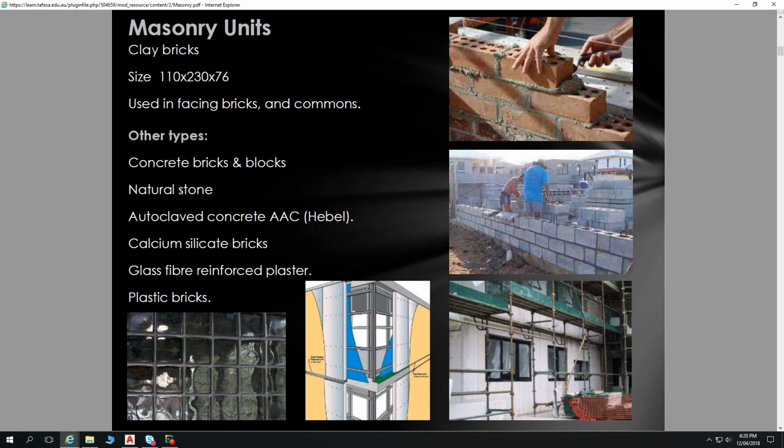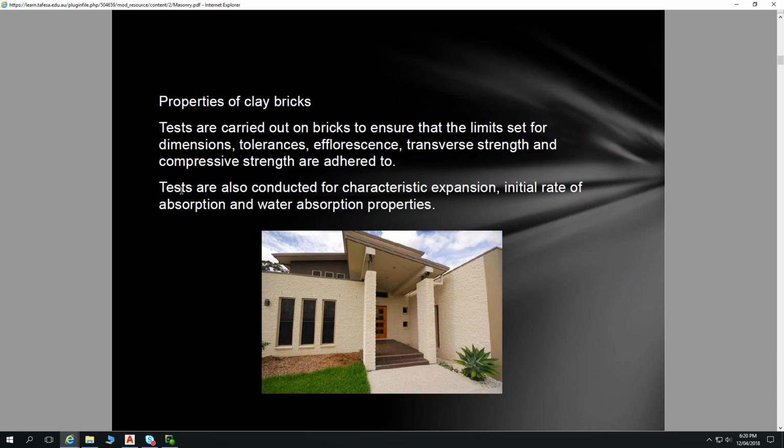But because we have to include insulation within our walls, it gets harder and harder to incorporate the use of stone, because we can't do just solid stone walls as an external wall. In climate zone 5, we have to have R1.5 insulation in the external wall. So there are issues with doing that, but also in laying stone as well. It's quite expensive and labour intensive.